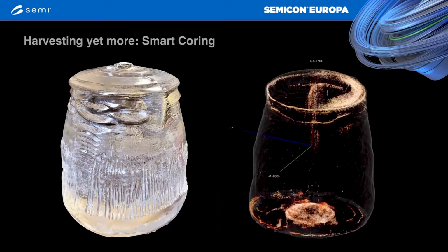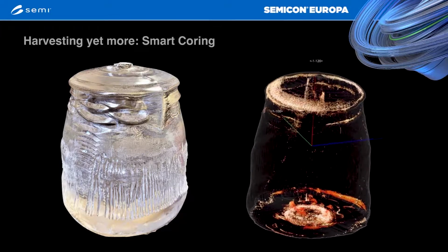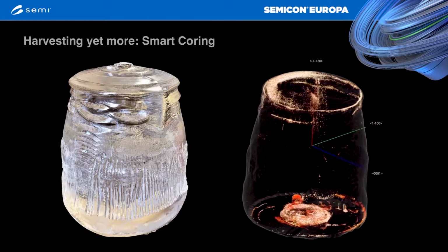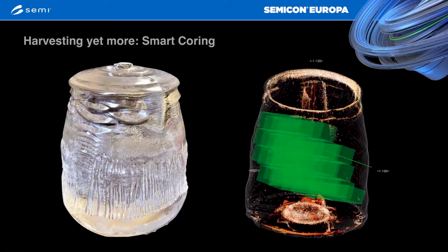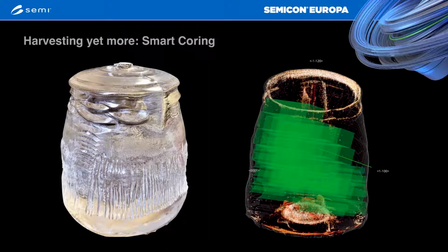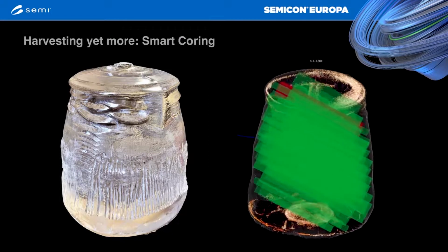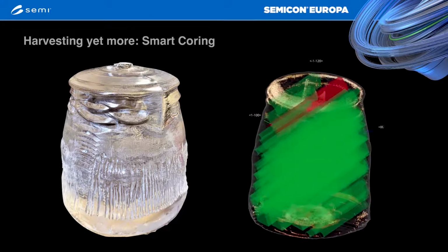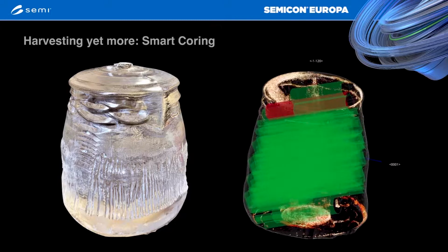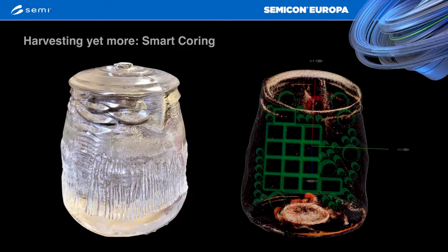As an example, here you see a 260 kilogram sapphire raw crystal grown by Czochralski method for producing semiconductor substrates. Like a typical Czochralski crystal, it has a complex, non-regular shape. Its digital twin on the right side is mapped to have rectangular and round cores of different diameters. The positions of the cores avoid volume defects as much as possible.